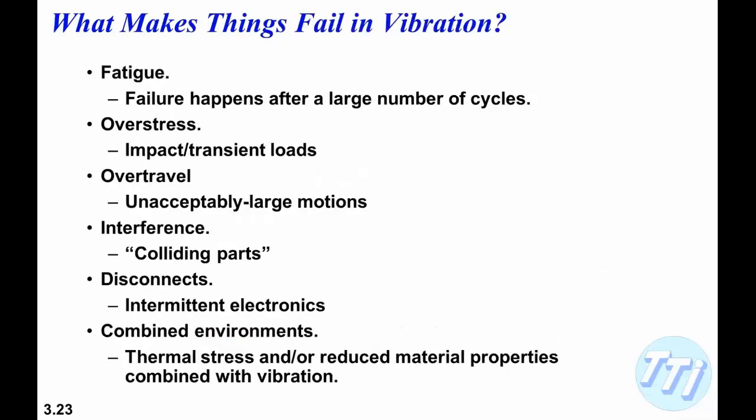So what makes things fail? Fatigue. Failure happens after a large number of cycles. This is one of the main things that the aircraft industry worries about. The wind turbine industry worries a lot about this. Another one is overstress, impact or transient loads, or in the case of wind turbines, a wind that is stronger than expected.